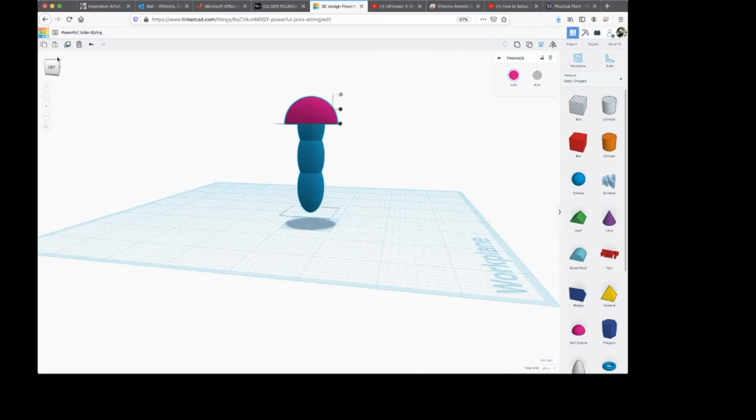join those together. So again, shift, select the first one, select the second one, come to the join tool, the group tool, sorry. So that's up in the right-hand corner. It's the second tool. Looks like a circle with a rectangle kind of joined together, right? The shortcut for that is Control and the G key at the same time. If I click that, you notice that it all turns pink, and that's your visual indication to let you know that that's been joined. So now I have 4 shapes that are a single shape.